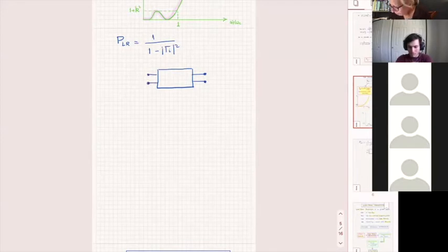So whatever power goes in here, after whatever reflections I may have at the front, all right? I may have, if this is connected to a source that has an internal impedance, and I have not matched the source with my 2-port network, which is my filter, in that case, there is going to be reflection here, so there is a P incident that goes inside the filter.